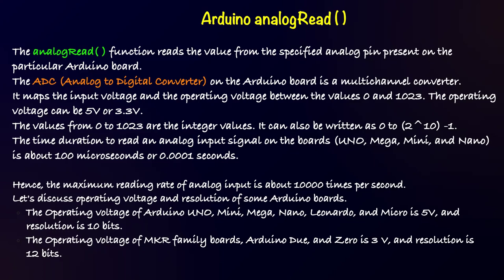A space can be provided for an external battery or cell, and that must provide 5 volt to the Arduino board. If it is providing more, then you need to add extra components to reduce the voltage to 5 volt and then apply it to the Arduino. That is how we'll be building the further projects.